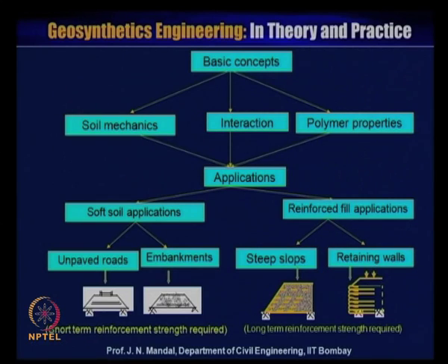The reinforcement interacts with the soil to develop axial forces through the bond and compatibility between the deformation of the soil and the reinforcement. So this interaction is very helpful for the basic concept and mechanism of the reinforced earth system.